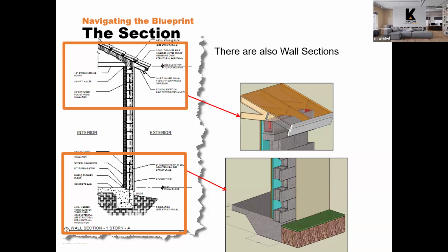Sometimes they might have three-dimensional details like this on the plan, but that's not typical. Usually the plans look like what they look like on the left here, but they're depicting what you see on the right. You see how this concrete masonry wall comes up and sits underneath the roof, how the roof overhangs it, where the trusses are located in relation to that exterior wall.